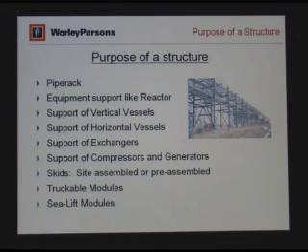There's always pipe racks, whether it's a single T-support for a single line, or you see a multiple level pipe rack here, probably an interconnecting pipe rack, 2 or 3 levels. We always provide support structures for pipe racks. We provide, in some cases, reactors. We provide either concrete or steel support structures and foundations for reactors. Commonly, the reactors are elevated above grade for maintenance purposes, so maybe 10 or 15 feet. So we provide either a steel or a concrete structure to support the reactor, and of course a foundation.